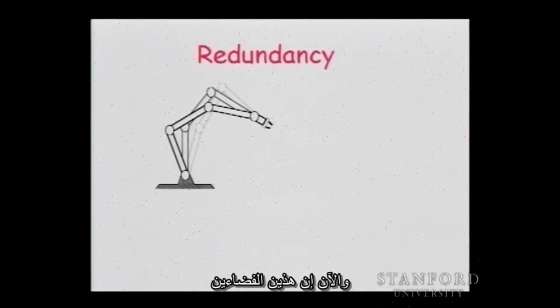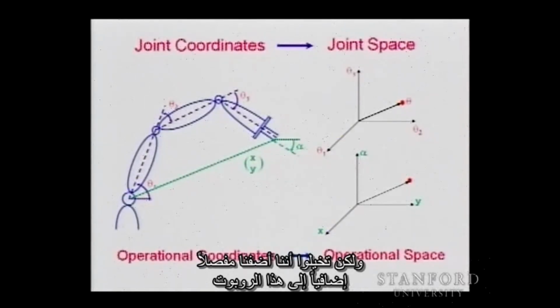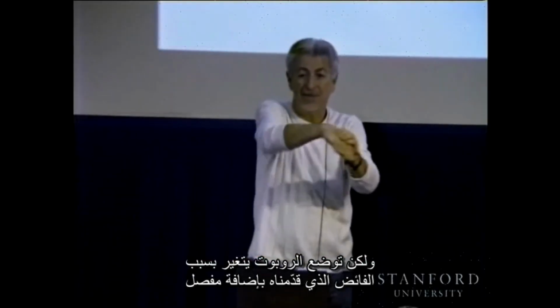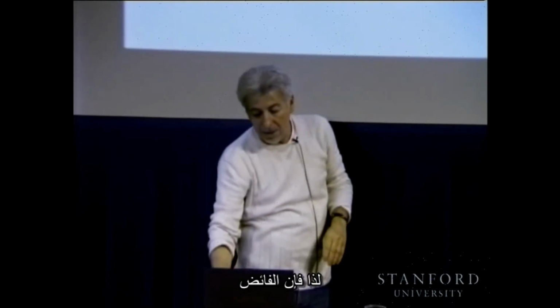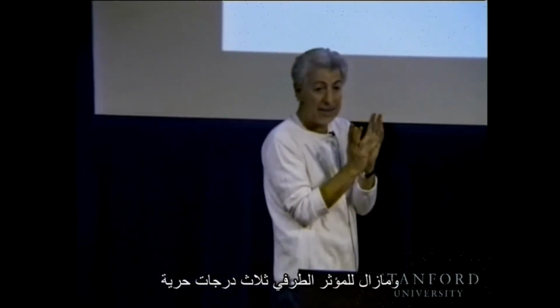Now, these two spaces: the first space is fully describing the configuration of the robot, but imagine that we add one more joint on this robot. The end effector is fixed, but the robot configuration can vary because of the redundancy we introduce by adding one more joint. So, redundancy: in this example here, you can see we have 4 joints, and the end effector still has 3 degrees of freedom.